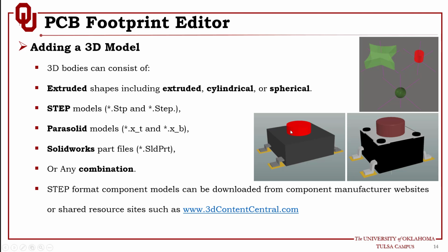Like you have a cylinder in here, and then you have an extrusion. Here you have extrusions. You combine 1, 2, maybe 3, 4, 5, multiple 3D extruded models to create this symbol. Because as you can see, these are the shapes. You can create pretty complex shapes in Altium Designer using these tools. Let me show you these tools.